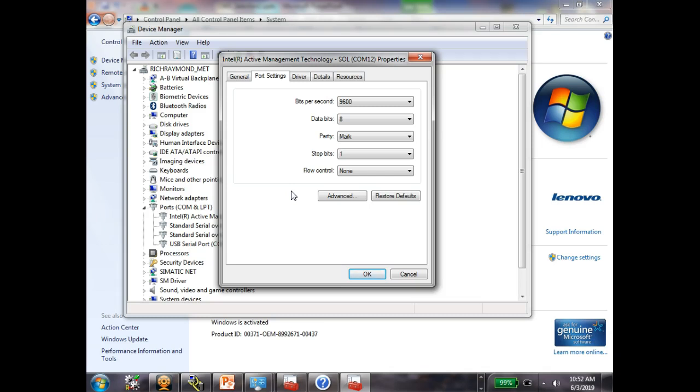Well, it comes in here and sets all this stuff up for you automatically. So normally most people don't go in and see this. You don't know it's out there, right? So when I hook up to this PLC, it's going to set the parity for me. Most of these guys use none. We had that problem a lot of times in the off-brand.